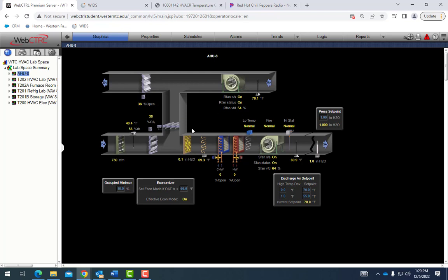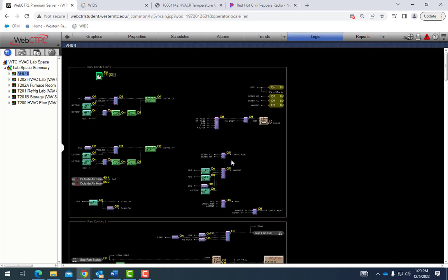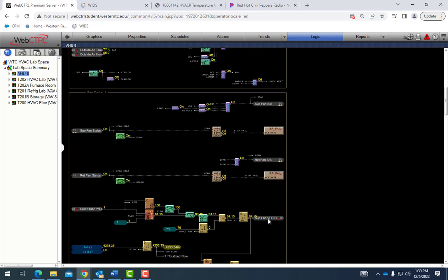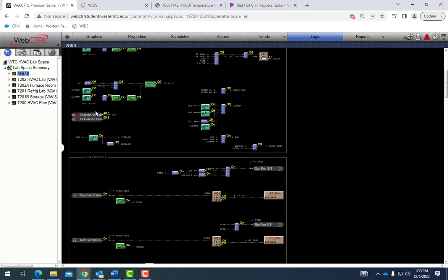What we're looking at here is basically the graphics of the program that we have. When we start actually building this, this is what we're going to be building. The graphics come after we do the logic. We have to have the brains behind why we're doing this. As you can see, there's a lot of ands or ors on the outdoor sensors. So: analog inputs, binary inputs, binary outputs, and then analog outputs. We learn those. Those are the biggest things that control our system.